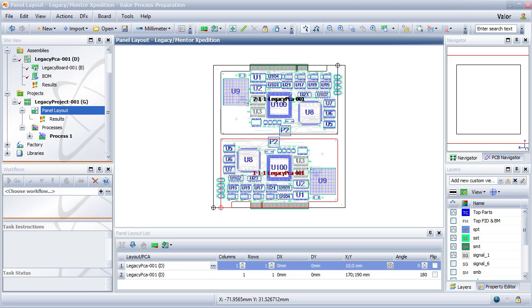With 70% of manufacturing defects being solder related, getting the right stencil in place is critical to managing the defect spectrum. The Valor Stencil Design module puts reusable rules in the hands of process engineers to better manage their stencil design process, as we shall now see. Stencils are typically created in a couple of ways. Either send your stencil guidelines to the stencil vendor, who then implements them for you, or resort to editing Gerber apertures across the whole board.